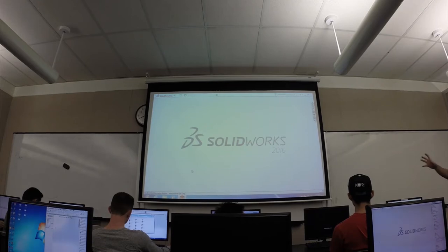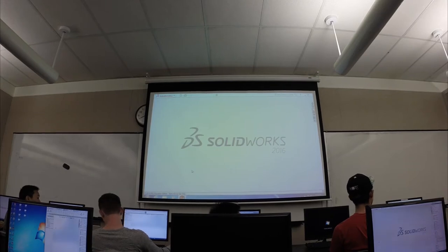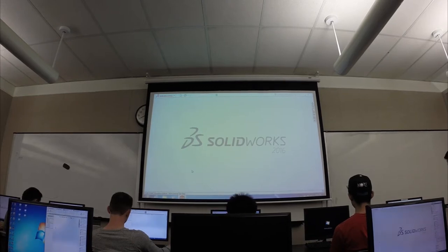Eventually, sometimes you'll notice when you have large assemblies or really complex parts and you try to edit a step from several steps before, SolidWorks will just crash, like, I don't know what to do with this part anymore. It starts freaking out. So that's a big part of it. Proper CAD practices are something that comes with time. And then we'll be going over that slowly just so you can get better practice of how to define things properly. Cool. All right.